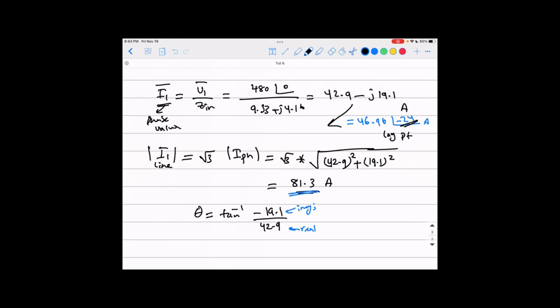Okay, and all induction machines are lagging power factors actually. Like we just discussed before in synchronous machines, a lagging power factor here is because it needs to get reactive power from the grid to build its own magnetic field, because it doesn't have a separate source for excitation. Remember, the synchronous machine has a separate DC source going to the rotor, which builds its excitation. So it has its own reactive power, and it can even give more to the grid, and that's the whole point. But an induction machine doesn't have an external source for excitation. It gets the excitation directly from the grid via its terminals. That's why it's always a lagging power factor.